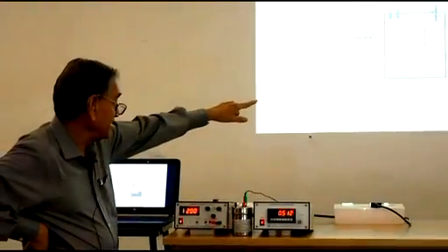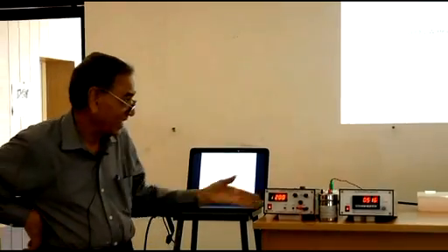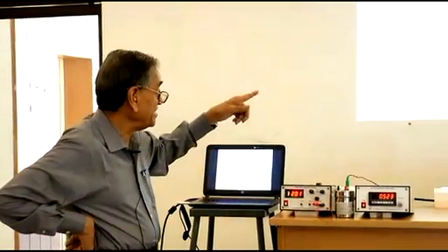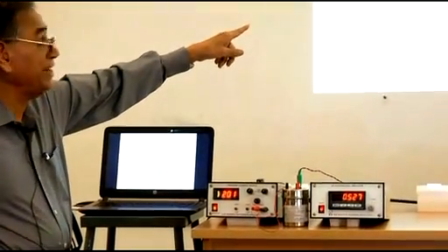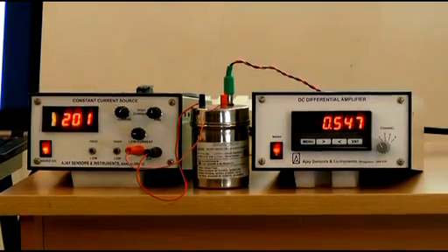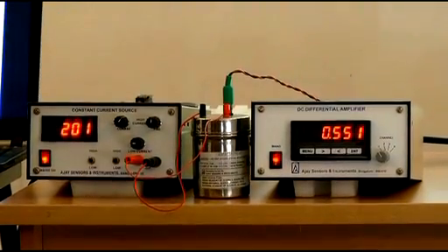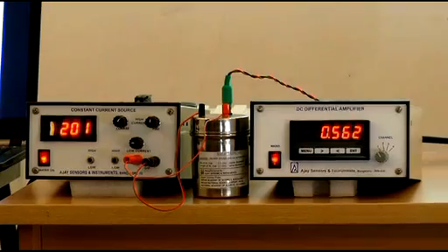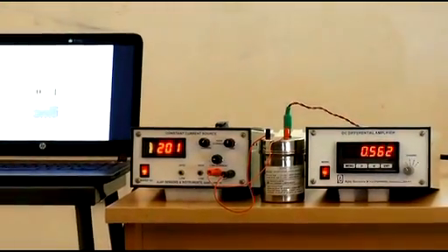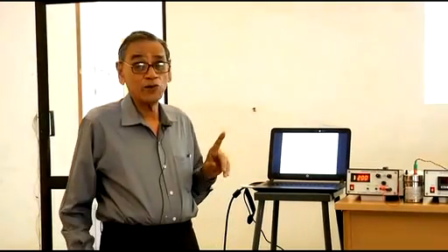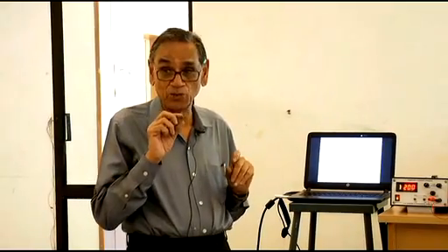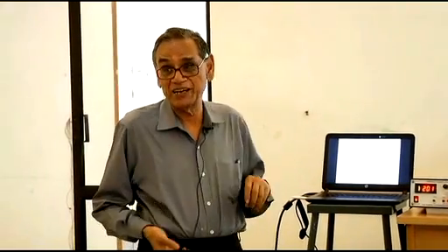The outer box is a stainless steel box, as you can see here, which is covered with a lid. Inside this box there is an aluminium cup which is marked red, and this cup is hanging from the lid by two nylon threads which have very poor thermal conductivity. I put the heater inside the cup. The 100 ohm resistors are fixed on the outside of a Teflon tube which goes into the aluminium cup.